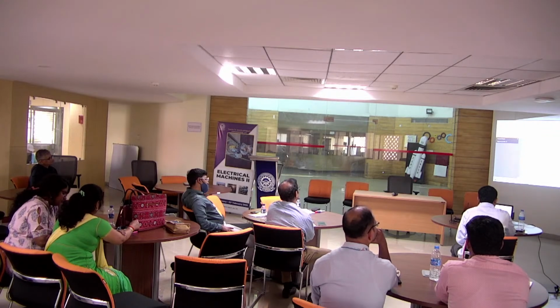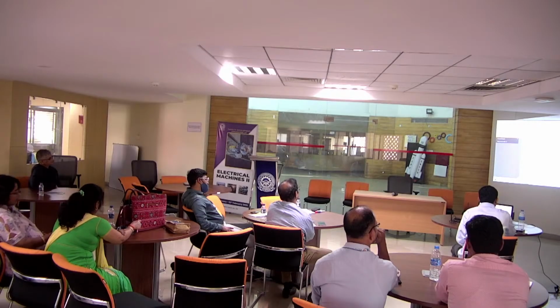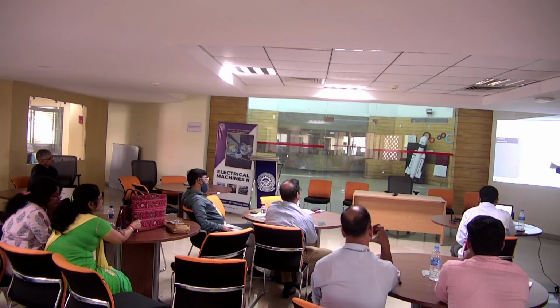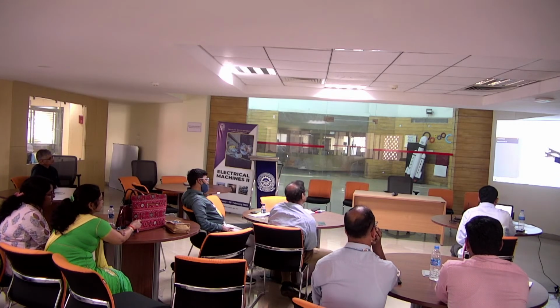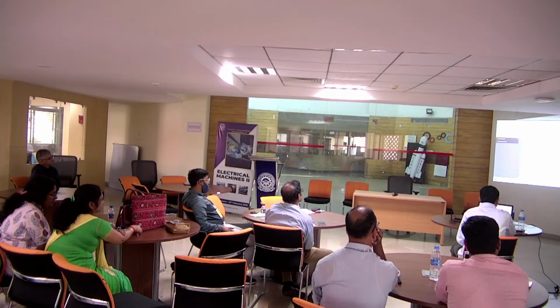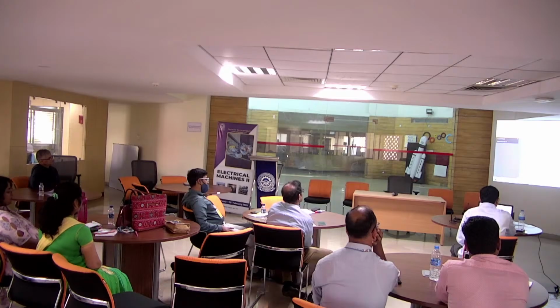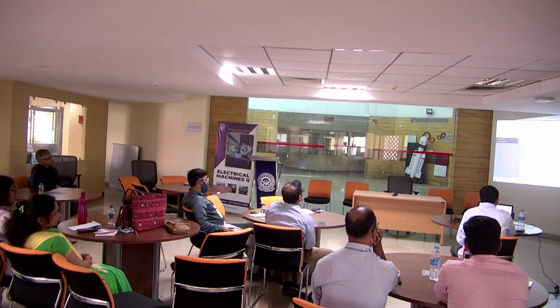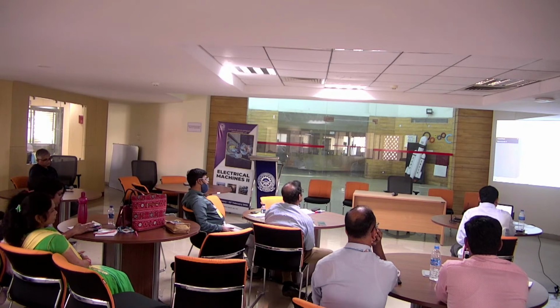Okay, we took the graph. How to do that in this particular platform, the virtual lab? After connecting and closing this, we varied this as per the procedure we follow. After that, connect the DC supply. Then check the speed here first. These are the sequence of steps to be followed while conducting the experiment. Then after that, apply the load. Then take down the readings one by one between the field current as well as the armature current.